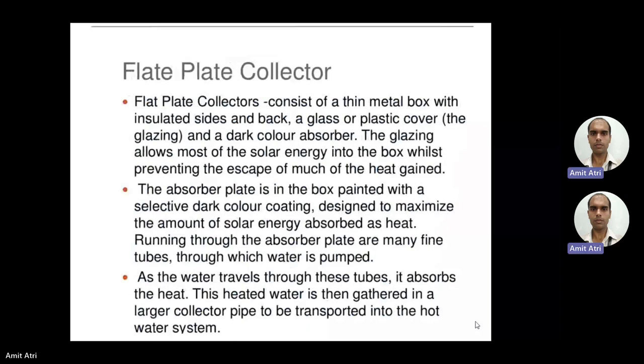Okay, so metallic flat plate absorber, tube or channels for the fluid, then transparent toughened glass sheet protection as well. Also one more thing the glass offers, that is greenhouse effect, collection of heat. Okay, then fiberglass insulation, so that the heat should not leak to the environment.